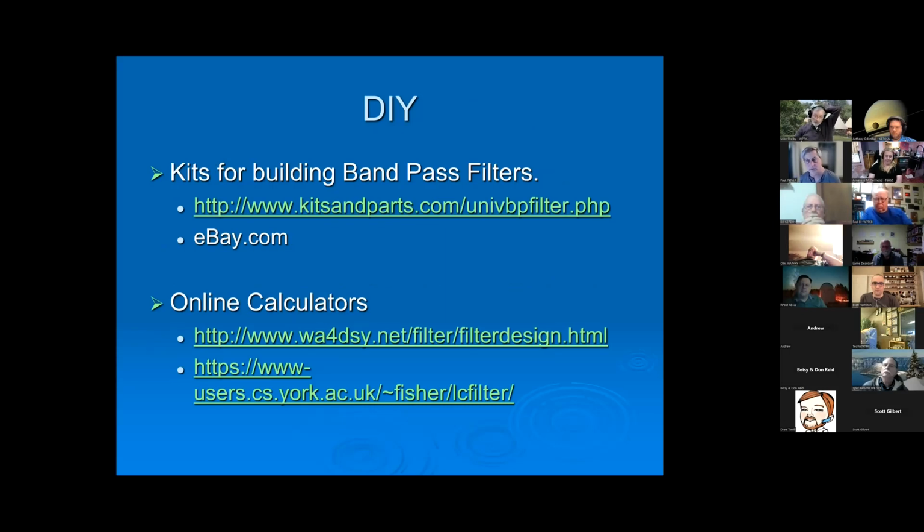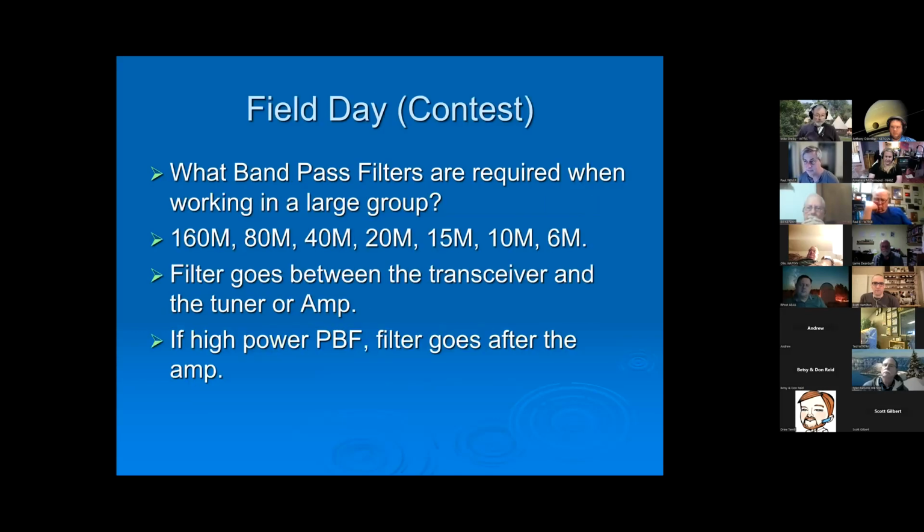So hey, Mike, could we go back to that slide? I think it's worth mentioning because it's an easy fail, and I've seen another club that I belong to burn up a few. So many of our radios have internal tuners, and when you just plug in and you're not really thinking, you could literally hurt the filter, damage it, or kill it. You need an external tuner to get the bandpass filter between the radio and the tuner.